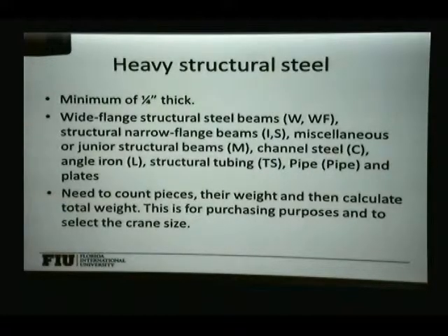The most common operation is to do all the calculations in weight. You have to either count the pieces or measure the pieces and then figure out what will be the weight of these structures and buy that by weight. And also figure out what is the size of the crane that you need to pick up these elements and move them on site.